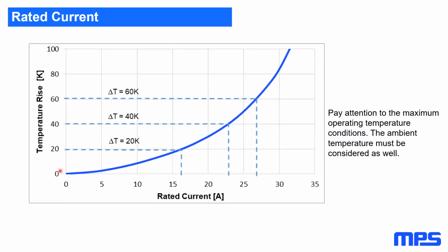So when we put some current, the rated current, what you see in the datasheet, some vendors have this value for 20, some for 40. There are some of them for 35. So it's not really a standard, which is what makes it so difficult at the end to compare the inductors. But if you understand how to read this value from the curve, it helps you a lot to compare exactly the same parameters on the same specification.